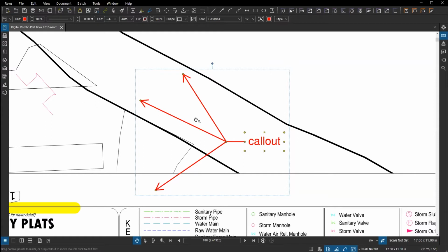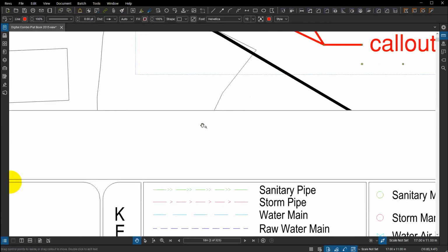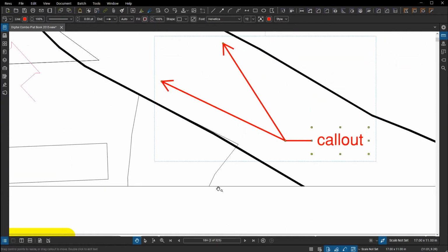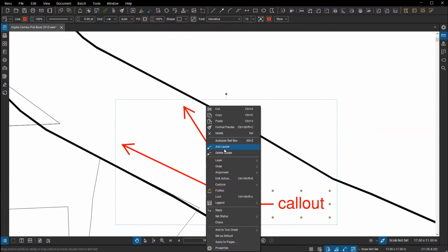And the same thing to go through and get rid of them. Maybe you dropped in 2 or 3 additional leaders and realized that, I really didn't want to have the extra one pointing to this overall destination. If you pick at the arrowhead itself, that little control point that's right here, if you shift and pick on it, it may be tough to see on screen, but there's a little minus sign by the arrowhead now that's going to subtract that leader out. So depending on where you choose to either add or remove, just shift will make that process a lot more efficient. It's faster than doing the right click, go to the menu, find the one you want, click it to add or delete.